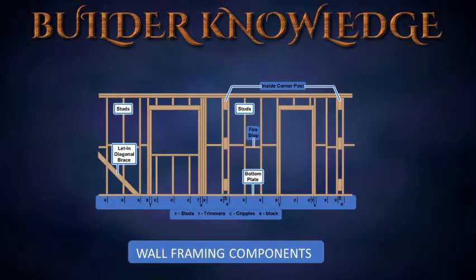Let's start out with wall and ceiling framing components. First is the plates. The plates are horizontal members that tie the studs together at the top plate, and the bottom plate or the sole plate of a wall. They furnish support for the lower ends of the rafters and ceiling joists. They also serve as a shoe at the bottom end of the studs. On exterior walls, the top plate is doubled to interlock all corners, help straighten the walls, and give added strength to carry the ceiling joists and rafters.